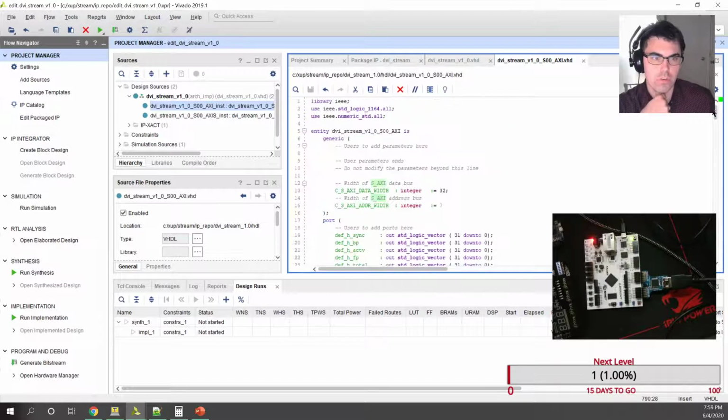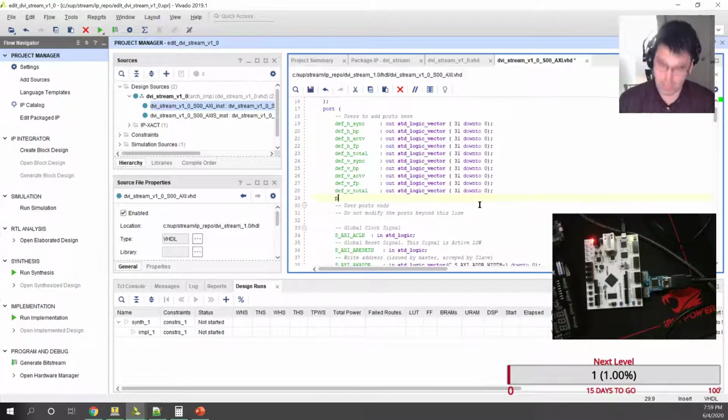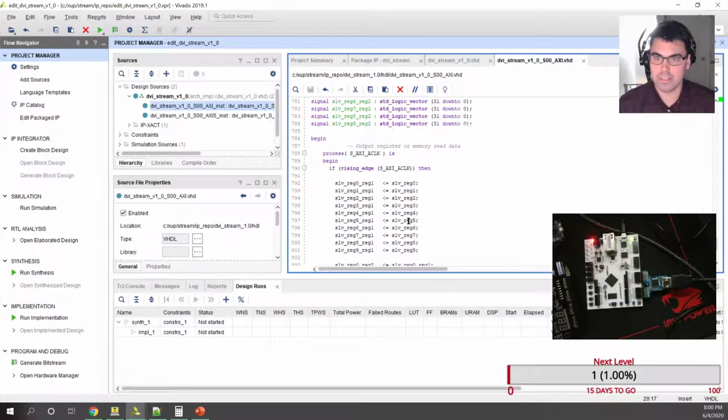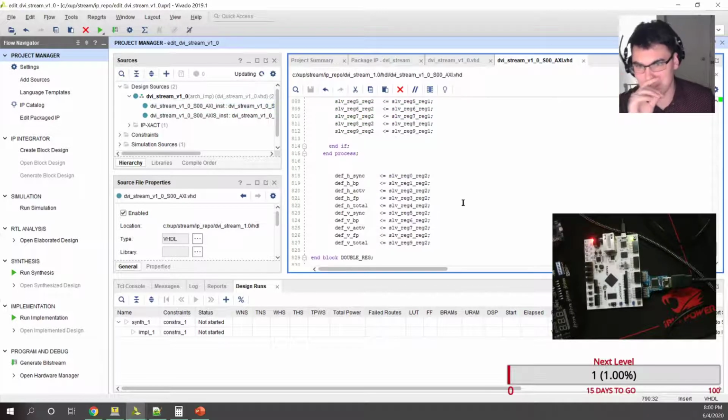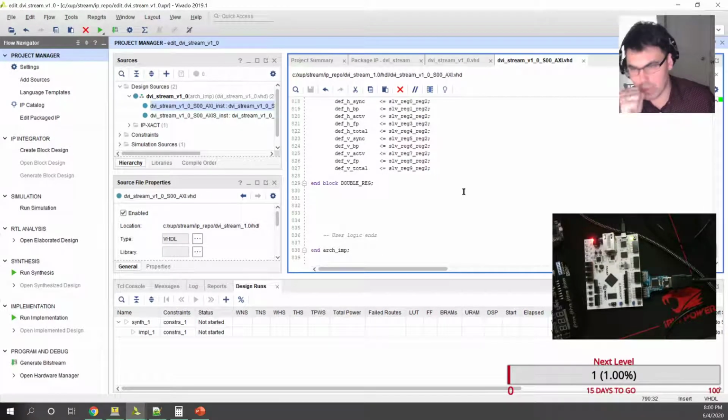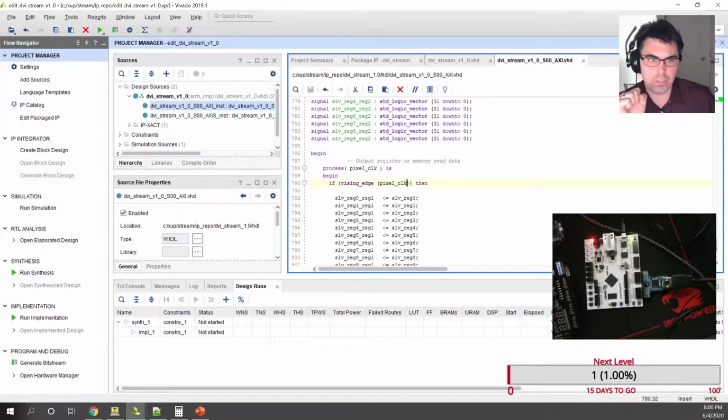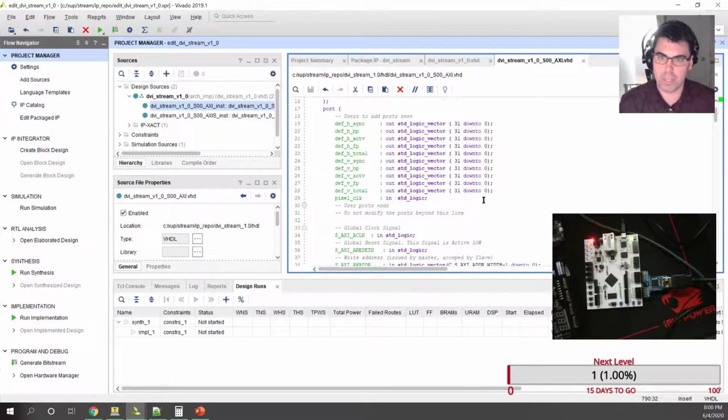Okay, yeah. So we're gonna add pixel clock to this guy. Pixel clock. In standard logic. My bad. I'm using the wrong thing to double register it. Double register into the domain that's reading it. New pixel clock. There we go. Back down here, this is all happening in pixel clock domain, to get some nice, good double registering happening. So when the signals come out, they will be in pixel clock domain. To do that, we also need to add pixel clock to our upper port connections.